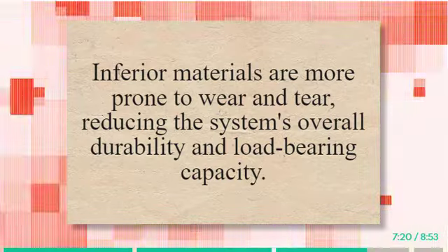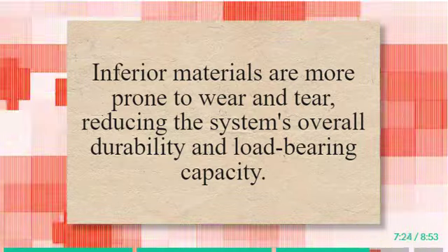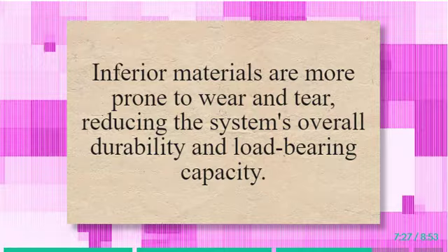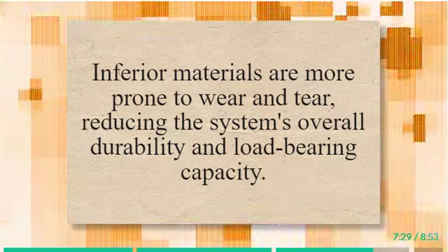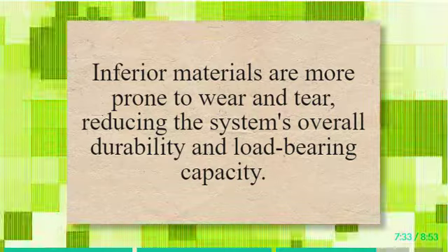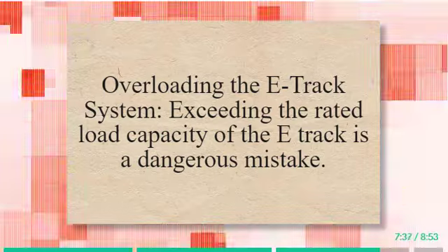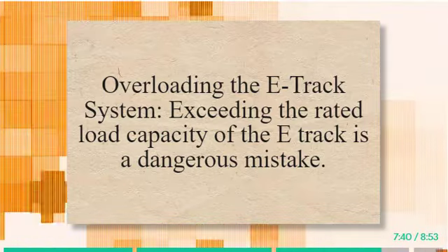4. Using low-quality E-Track or hardware. Cutting costs by choosing low-quality E-Track or hardware can lead to disastrous consequences. Inferior materials are more prone to wear and tear, reducing the system's overall durability and load-bearing capacity. Invest in high-quality E-Track and durable mounting hardware to ensure safe and reliable load securement.